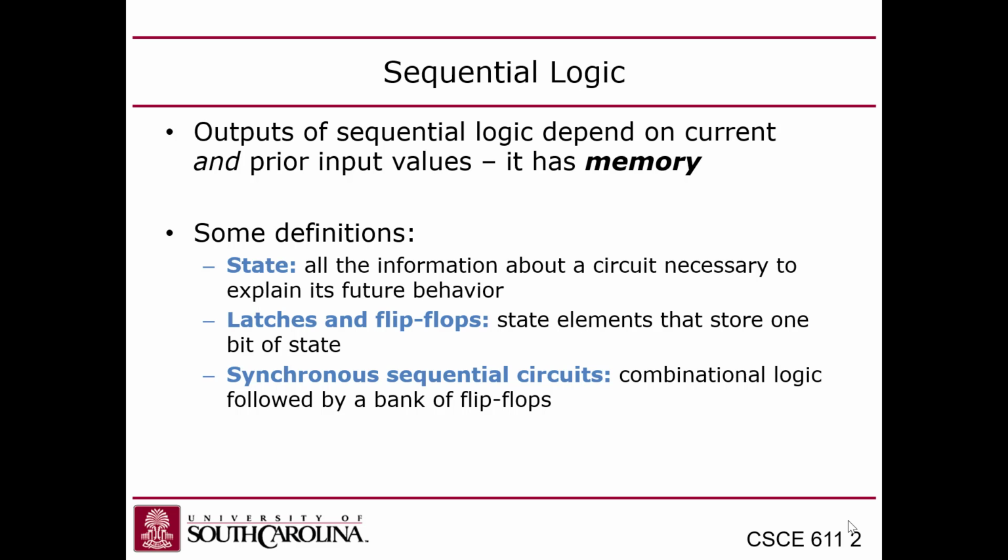And sequential logic circuits include, in addition to gates, memory elements, which are generally flip-flops. And there's also this concept of a latch, too, which I'll cover in a minute. But basically, these are the logic elements that keep track of the state. And then a synchronous sequential circuit refers to a circuit that includes both combinational logic and these memory elements, which they refer to as a bank of flip-flops in this slide.